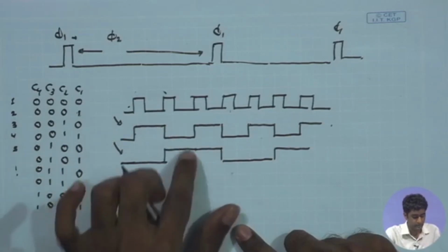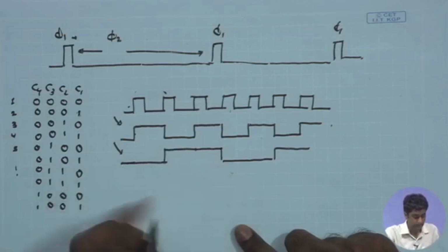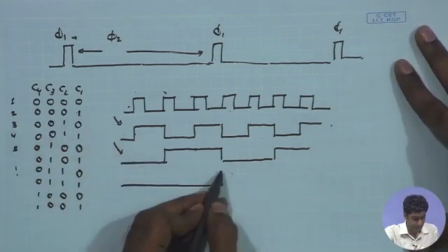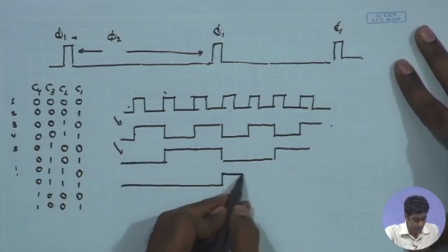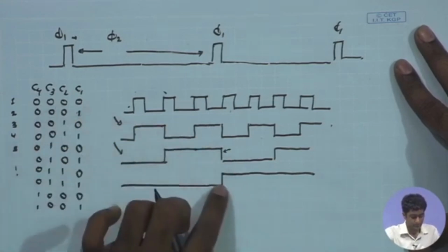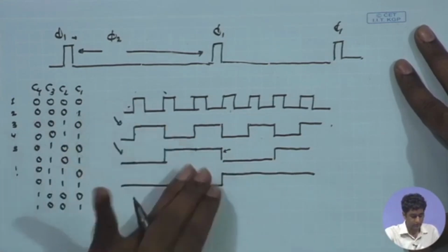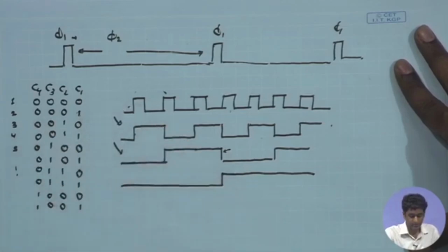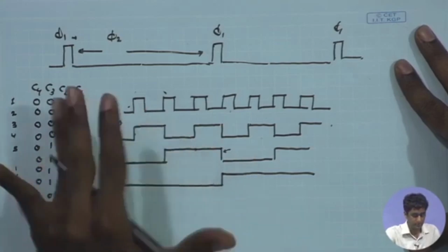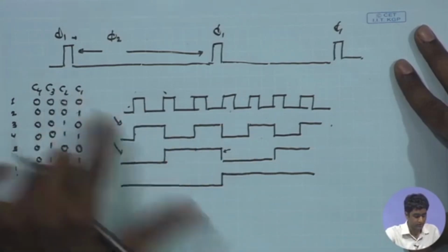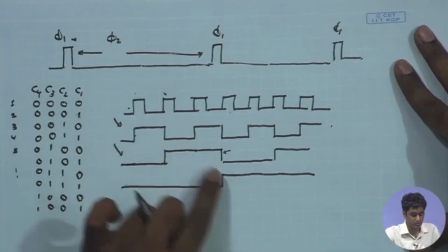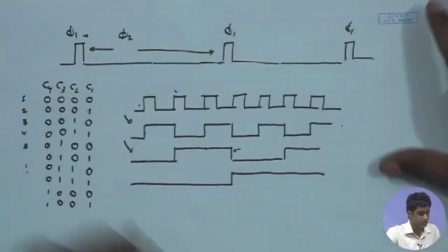Likewise, I assume that whenever C2 makes a negative going transition, C3 is going to make a transition, and the C3 waveform will be looking like this. So, at the negative transitions of C2, C3 is going up. Subsequently I have the frequencies of the clock getting divided by 2. So, this is the operation we would like to implement using digital circuitry. The circuitry implementing the counters ultimately should be able to implement this divide by 2 operation, starting from the original clock and going on dividing the clock by 2.